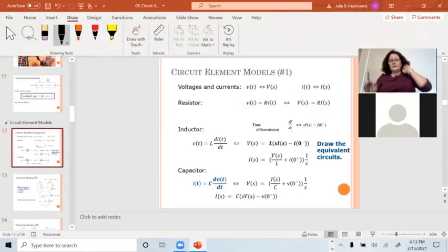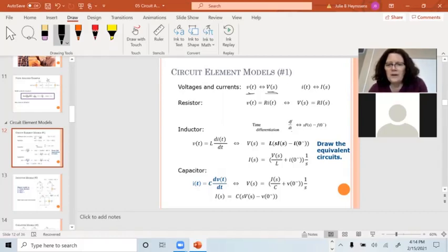Okay, and I really went through and rewrote these slides this morning. I actually have time to do that now. Remember the voltage sources, they just get transformed. We take the Laplace transform of whatever their function is, and we put that in the S domain. Same thing with current sources. Ohm's law works in the time domain. It's also going to work in the frequency domain.